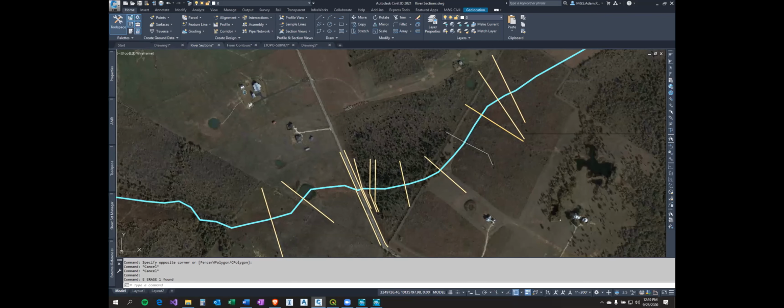I was still getting my lunch when you did the export the DEM. So you basically bring in the topo from the city, and then you create a surface based on the topo and then export it as a DEM, and then you can import it into RAS Mapper. Is that what you did? You can do that. What I did ultimately was just use the DEM from TNRIS. Okay.